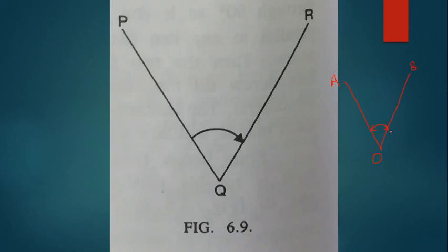That means we take a horizontal reading with a clockwise swing, and repeat the same angle measurement 3 times. Then we change to the other face, that is face right, and again we move clockwise with the swing right, again taking 3 turns, that is 3 repetitions. Here the final reading of the first observation will be the initial reading of the second observation and so on.